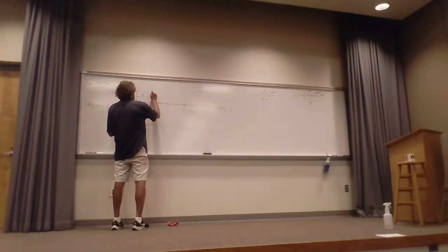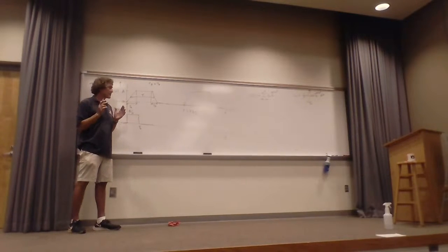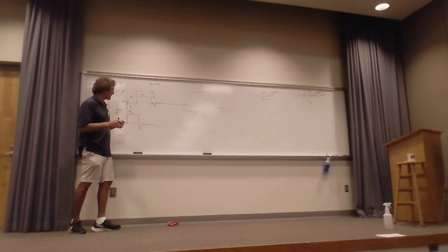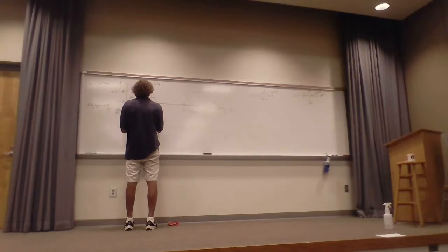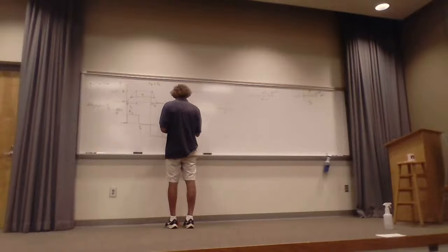Matter of fact, I didn't put this down here, but this is tau fall. And they almost always make tau fall equal to tau rise, and whichever one is worse, they use. So normally, if you're looking at the bandwidth, they'll use the shortest, or the minimal value, for the actual values of tau. Then if I come down here, at this point, we'll assume tau fall is tau rise. Then it goes negative, and the value here would be minus A over tau rise. And it will repeat itself. We'll just keep on repeating.